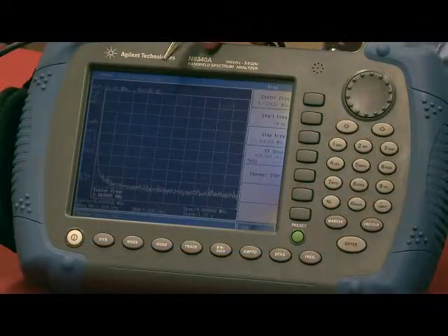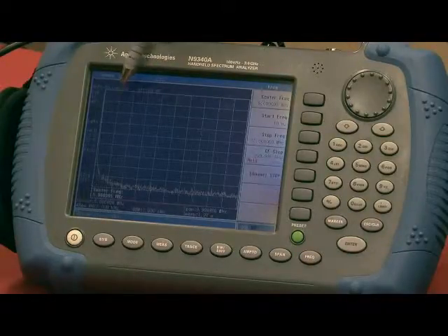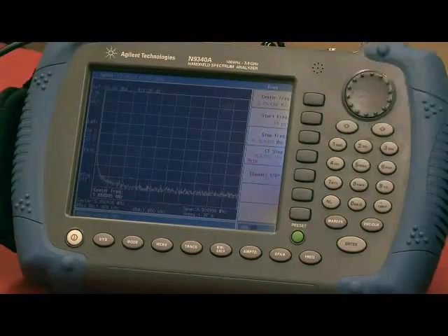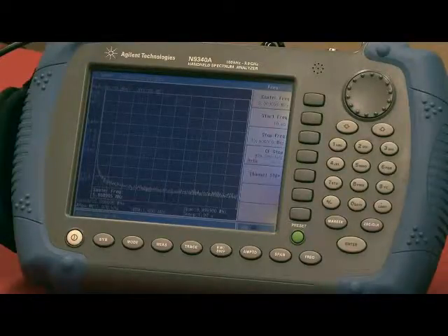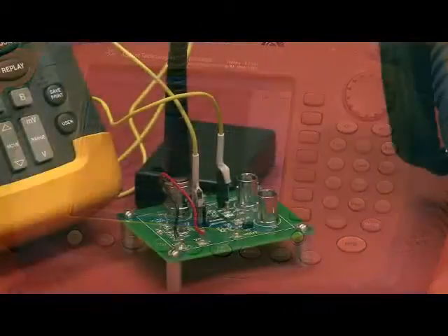I've now moved to the output of the high-performance LDO, and again you can see the ripple blocker has eliminated all of the DC-DC switching content. At low frequencies, we're getting in excess of 80 dBs of rejection from the LDO, and at high frequencies between 40 kilohertz and 4 megahertz, we're getting in excess of 55 dBs rejection. The ripple blocker is unique in that it can offer this kind of rejection with a very low requirement for headroom.